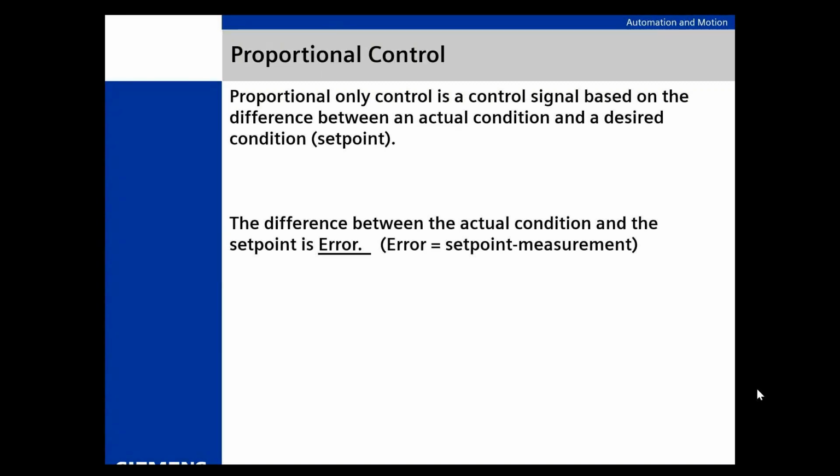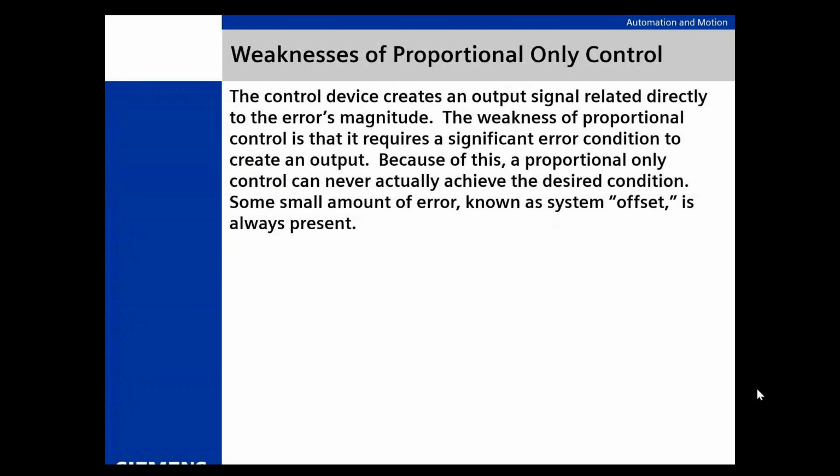So it's going to kind of lollygag around. And here is the bottom line. It's probably never, ever going to be on set point. It'll pass through. It'll overshoot and cool your house down a couple extra degrees, and it's going to start to fall. It'll go right back through set point and fall and fall. Now it's going to turn the air conditioner back on or off, whatever it is.